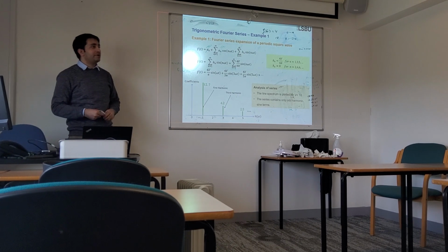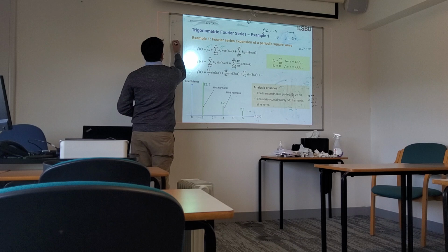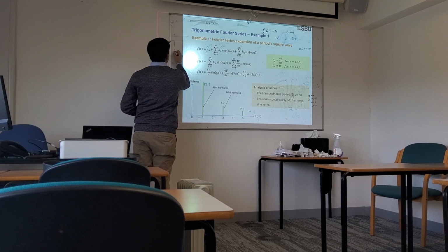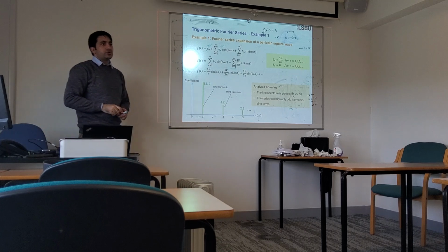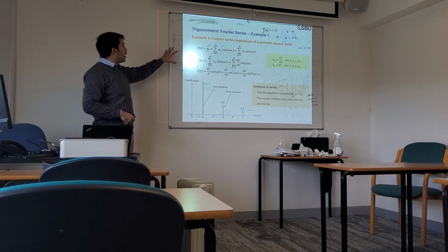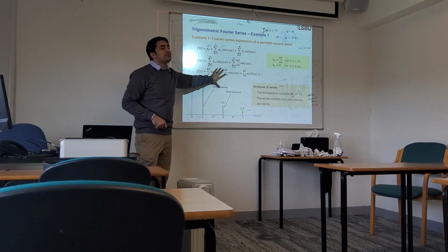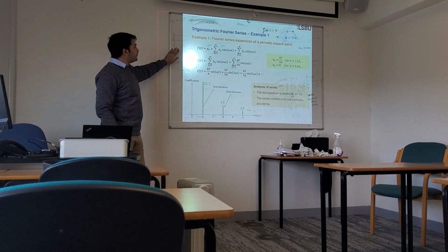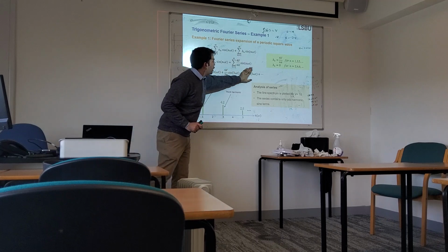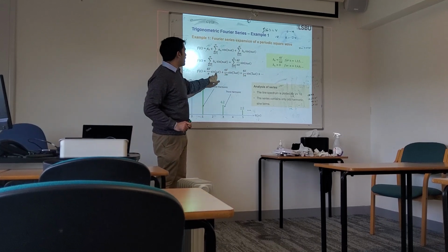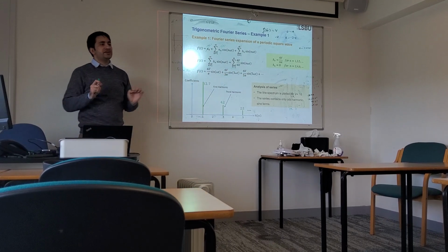But this is not possible. Why not possible? Because when we take a DC and convert it into AC, sometimes it is distorted, so this is not pure AC. In order to analyze this signal, we break it into a Fourier series. If this was a pure AC, all other terms would be 0. You would only have the omega term, which is the 50 hertz term.